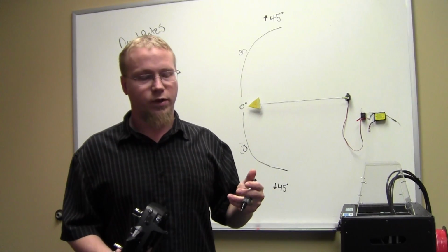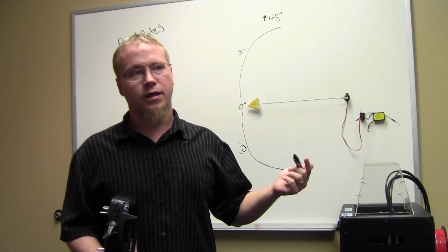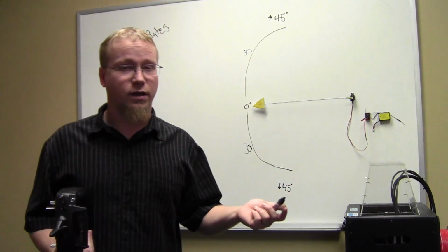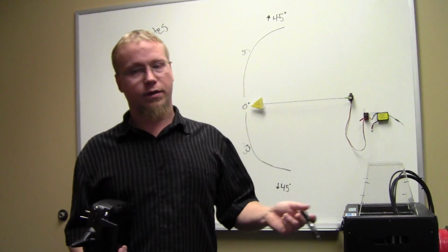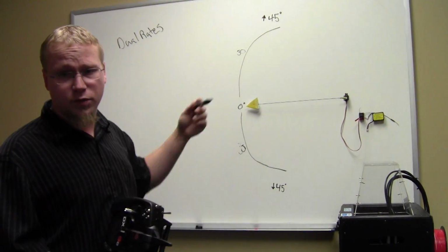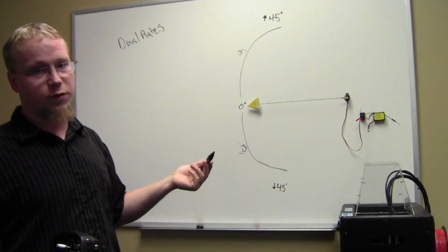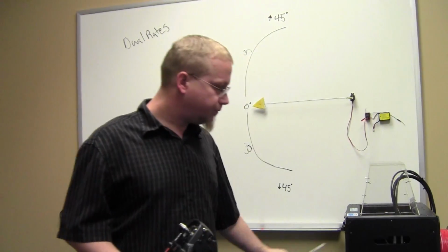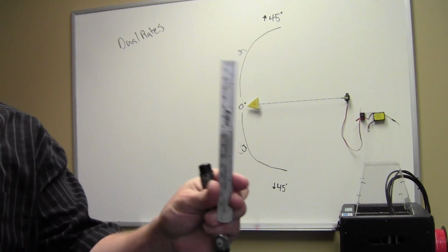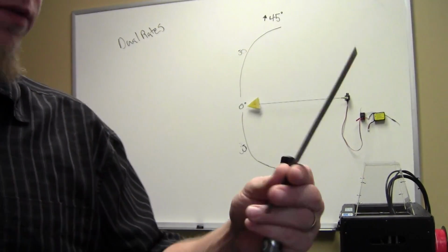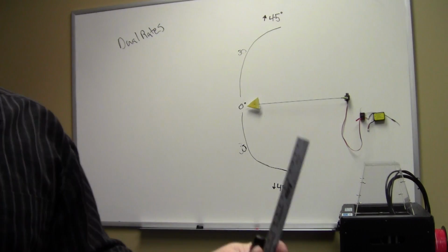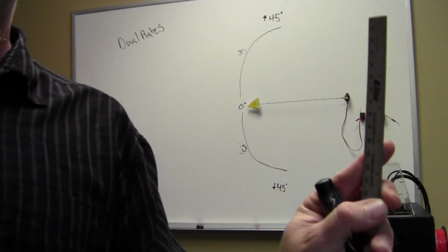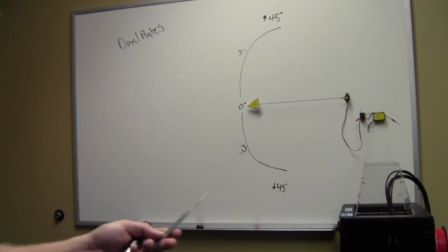All right, so let's say we're looking at our manual, and it recommends 20 millimeters up for full high rate and 15 up for low rate. So instead of degrees or percentages, a lot of times they'll give you a measurement. For a measurement, what we like to have is a ruler. I've got my trusty E-Flight ruler. It's not going to be quite big enough for our example here, but for a control surface, this little guy works great. Pretty much any precision ruler like this, with millimeters on it, is what you want.